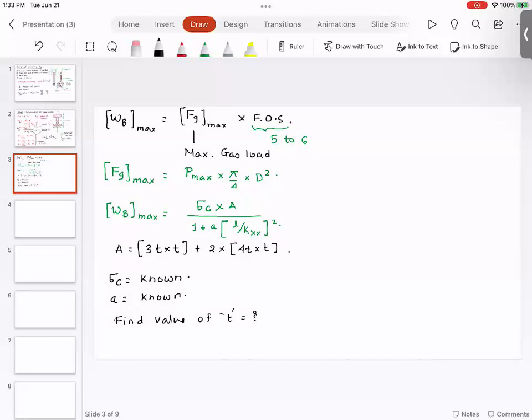So remember this, when you go to design, very rarely you will actually do something from scratch. You will design, you will have rough dimensions, and then you will go and try to get a catalog item. If you don't find the catalog item, you'll find a catalog item that is close or that can be modified and then actually use that. So that's why a design data book is always used in design.